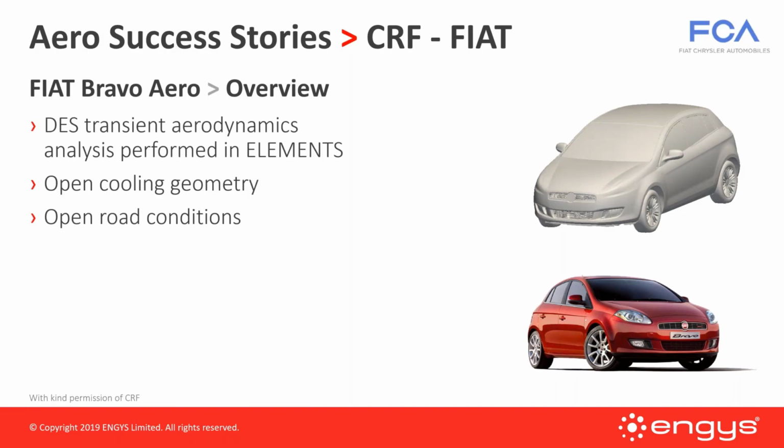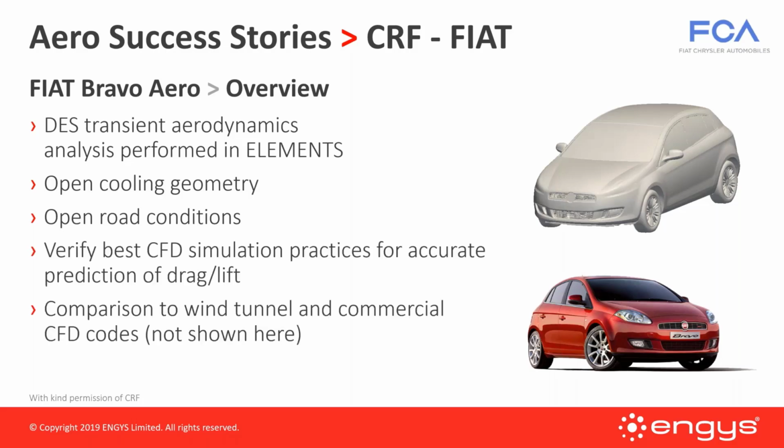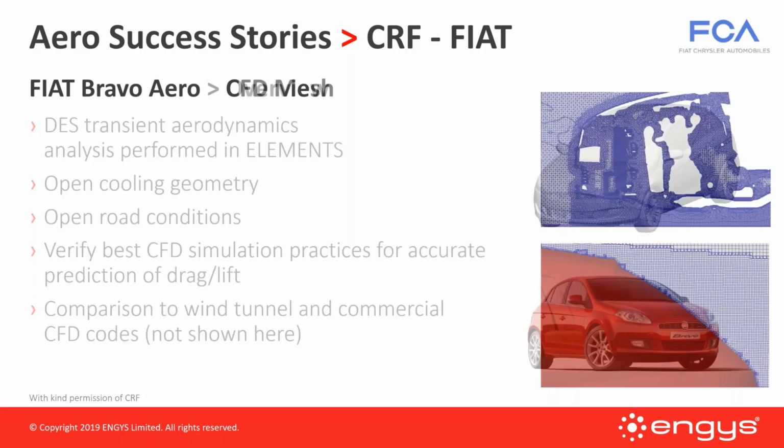This used a DES transient aerodynamics analysis, and this was also performed in Elements. It was an open cooling geometry, open road conditions, and the goal was to verify the best CFD simulation practices for accurate prediction of lift and drag. They compared the wind tunnel and CFD results of various commercial codes. In these slides, I am not showing the CFD codes because I don't have those results. So we're only going to show just Elements versus the wind tunnel results.